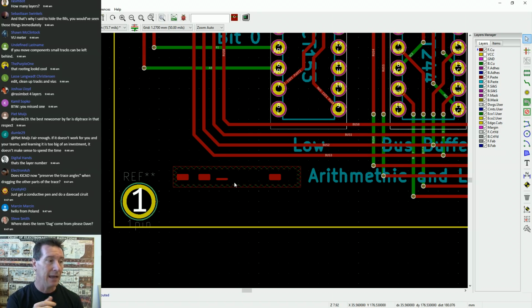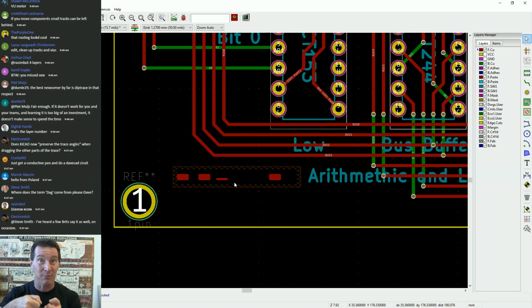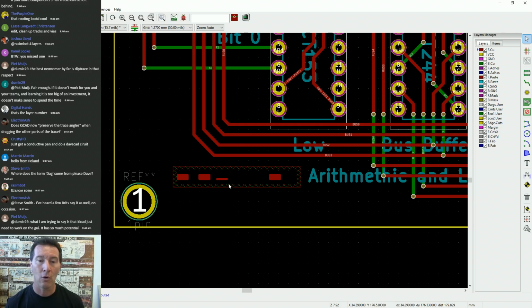You can see the alignment of the masks and everything, solder mask, silkscreen, top and bottom, copper, whether or not they've over etched or under etched. You can get in there with your micrometer and actually measure if your 4 thou track is actually 4 thou, how much they're out by, have they over etched it, all that sort of stuff.